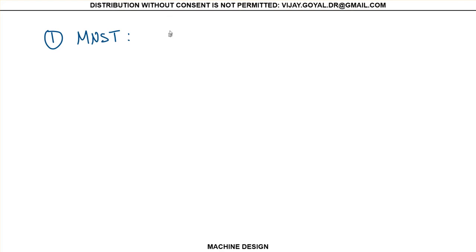That basically says the factor of safety is either equal to sigma ultimate tensile over sigma 1, or it uses sigma ultimate compressive over sigma 3, depending on the case that you're working with.